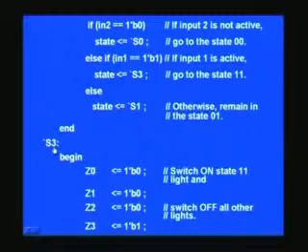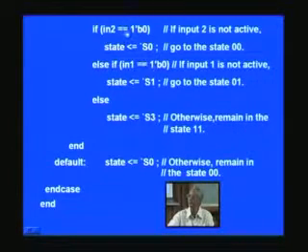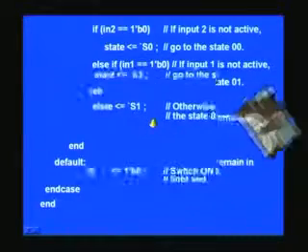Say we are in S3 state, and in S3 state, let us say in2 is 0 here, but when you come here, it implies in2 is 1, otherwise it can't enter this point. So then here also, if this is to be processed, this is the condition to be met. So if you are to come here, you had to have in1 equal to 1. That means when this is being executed, it has to be in2 as well as in1 both 1. So let us verify that.